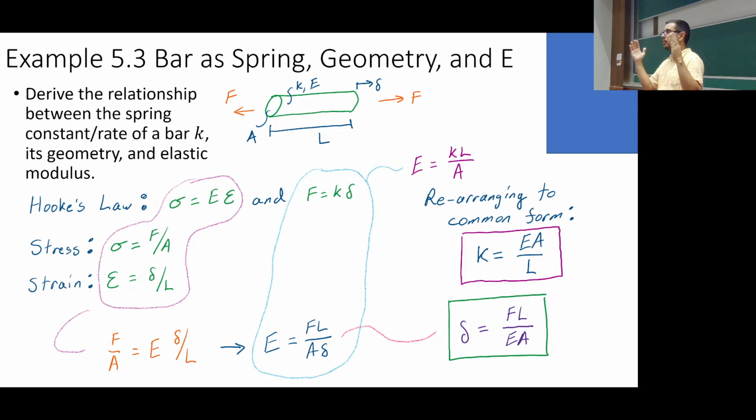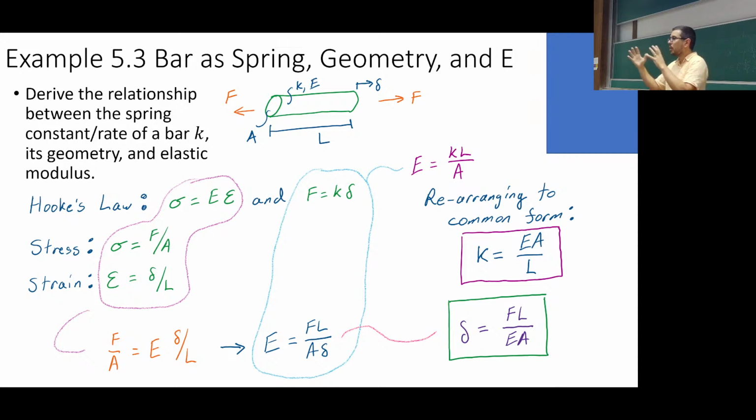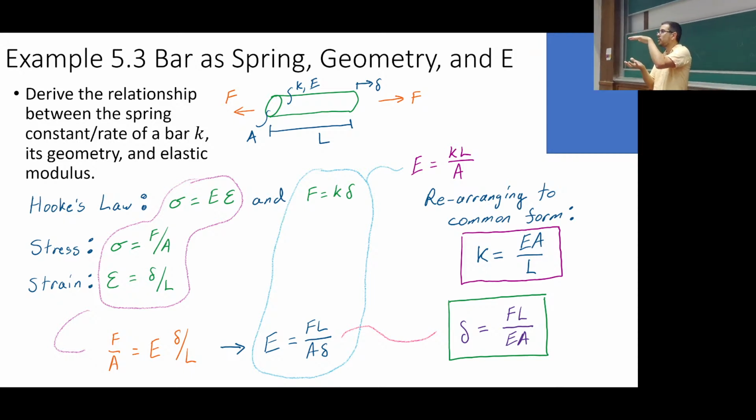Okay. I'm applying force on the ends, and I'm looking at the overall displacement. How do I solve for the effective stiffness? Yes? That's 1 over K effective equals 1 over K. Exactly right. So now you can break it down into, okay, here's the effective K for this region with a small diameter. And here's the effective K for this region with a large diameter. All right? And once I have those two Ks, it's like springs in series. So you can make some pretty good approximations.